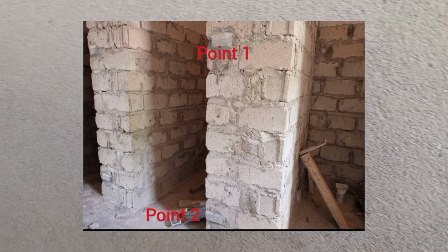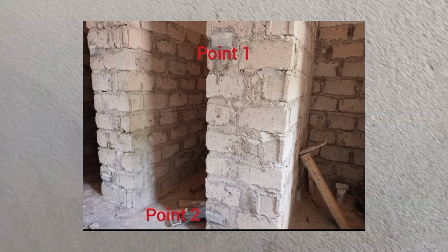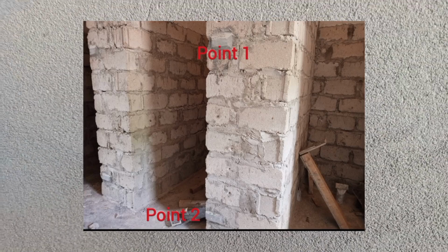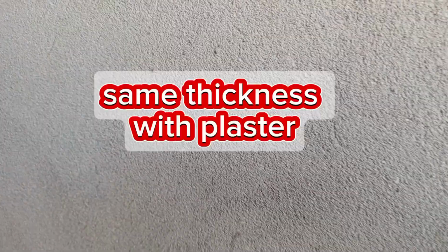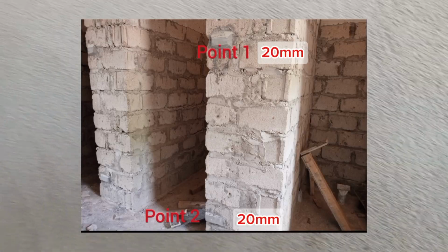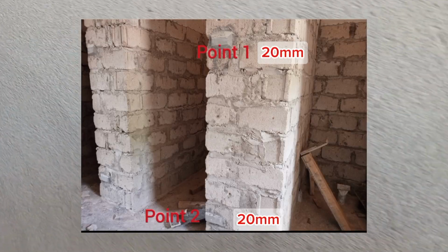For example, if you have been told that the thickness of the plaster required is 20 millimeters, then the points you put on the wall will also be 20 millimeters thick, such that when you apply your plaster, it will also be 20 millimeters thick. Your first point on the top will be 20 millimeters thick, your middle point the same thickness, and the last point also 20 millimeters thick.